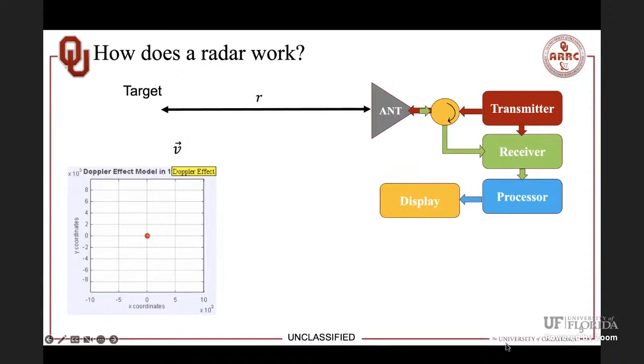In order to determine the angular location, think about it this way: if I have just one light bulb illuminating all the locations, and you have one received signal, you really don't know where that location is. So what radar does, instead of illuminating all directions all over the place, is send out a very, very narrow beam, like a flashlight, with very concentrated energy in a specific location.